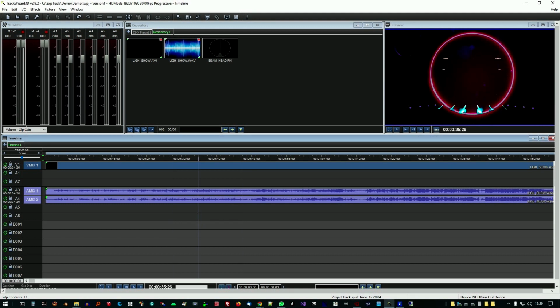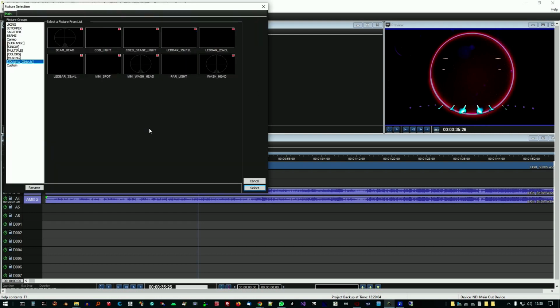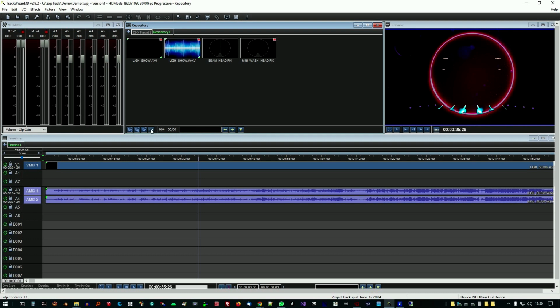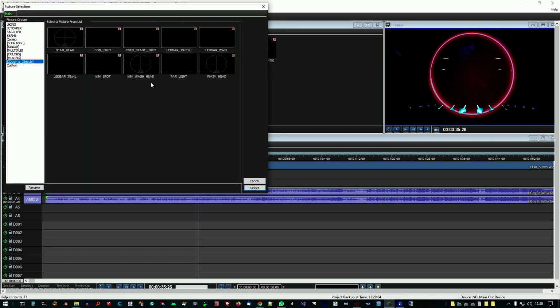Now let's add the DMX devices. By opening the Fixtures window from the repository, let's select some generic virtual fixtures. The generic lighthouses are equivalent to the real ones in terms of programming and allow you to test the scenes in case we don't have real lighthouses available, or if we want to carry out simple lighting tests. Let's take for example some rotating heads. Let's add some fixed spotlights for diffused lighting. We select some beam-type rotating heads. Adding everything to the repository.